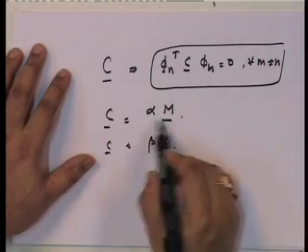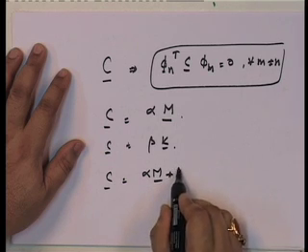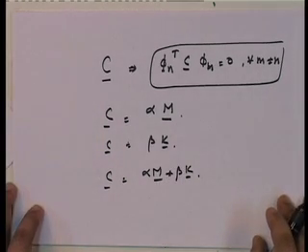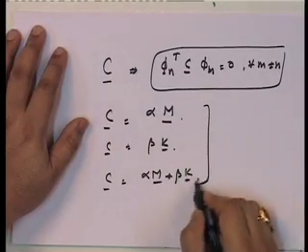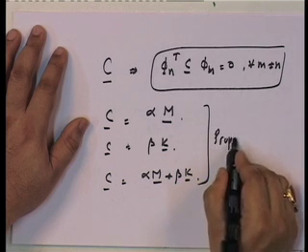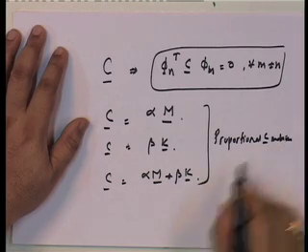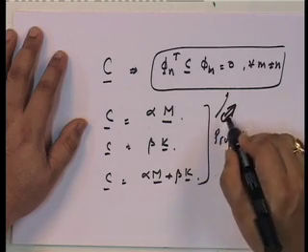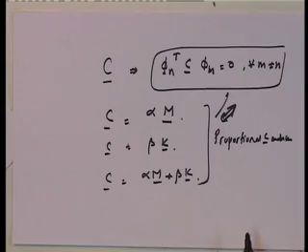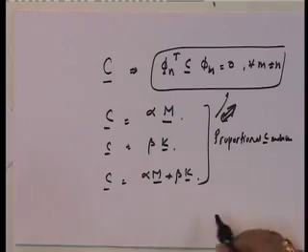We know that if this is this, then we have the situation where it is a linear combination of mass and stiffness proportional. Okay. So, these are what are known as proportional C matrices. If these are there, then this is automatically satisfied, because we know that phi is mass orthogonal, stiffness orthogonal. So, if they are of this form, we know that this is true.